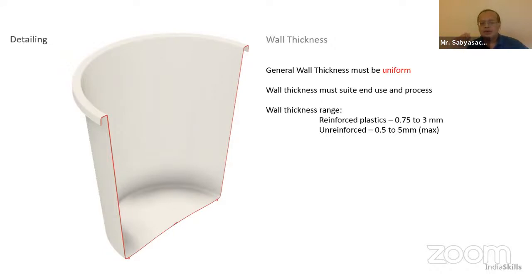That is the first thing that you can choose. Of course, depending on the kind of usage and the material choice, the thicknesses will change. Say, for example, you have a medical product, or something like a mixie. There, your wall thickness might be about 2 mm, 2.2 mm.